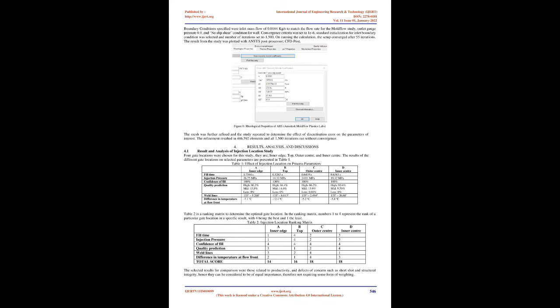ejection of the part. Having the gate centralized along the parting line represents the other alternative to achieving even filling of the cavity, albeit with a longer flow length resulting in higher injection pressure. The outer center position moves the witness mark to a less obvious position. The inner center position further enhances the visual appeal by effectively hiding the witness mark. The fourth position, inner edge, acts as a counterintuitive control position that is obviously expected to result in an uneven fill but may reveal other benefits from the simulation study.